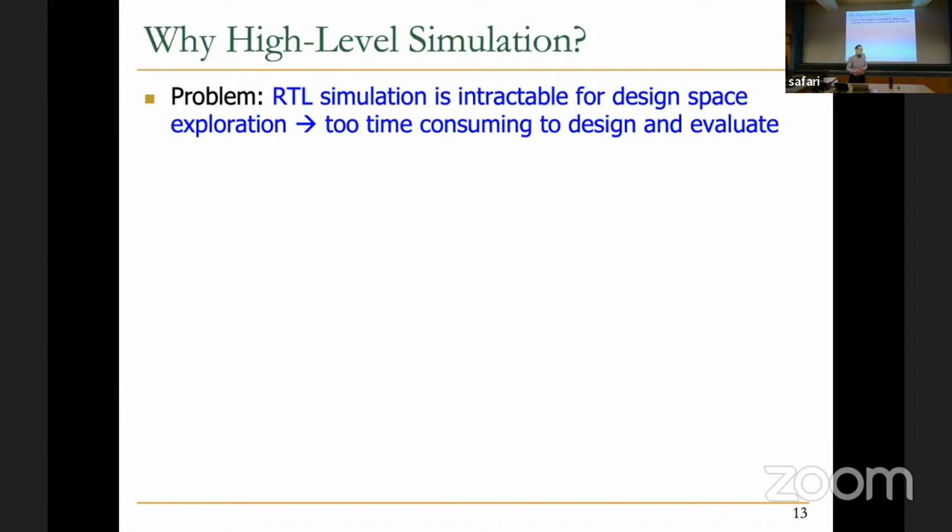So high-level simulation is essentially high-level language simulation, C simulation. You could actually design simulators in Python, etc., that abstract away what goes on in hardware, right? For example, you can say, if row buffer has the row I'm accessing, latency is equal to this, right? Clearly, that's not how hardware works, right? I mean, there's some construct that implements this, but those are gates, and those are some logic over here. So basically, you can have high-level language constructs to design a simulator.